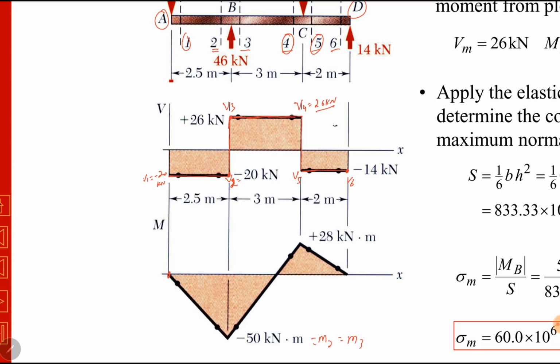So we have to connect point A with point B, and we will connect it with a linear line. Why have we connected them with a linear line? Why not with a curve, a parabolic or a cubical curve? We will derive the reason later, but currently just know the fact that if shear force is constant between 2 points, bending moment will be linear.